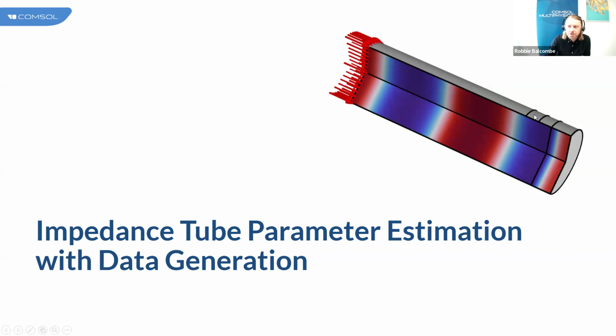We can use some microphones to measure the acoustic pressure versus our frequencies. And through parameter estimation, we can actually work in reverse to match the results of a simulation to our experimental data in order to work out what material parameters would be needed to characterize our porous material to match with our real porous material.